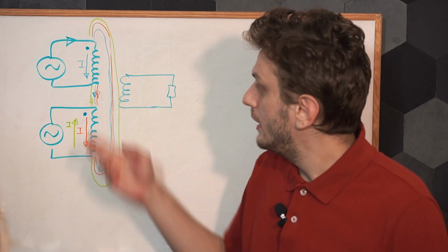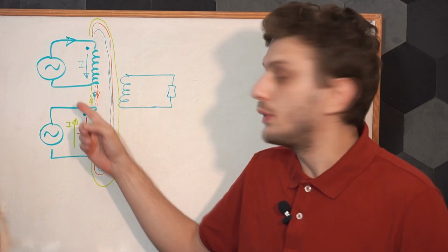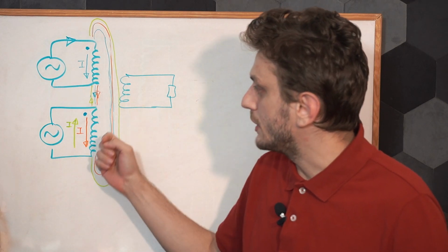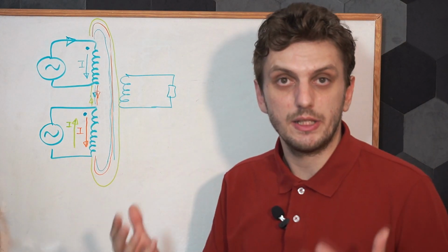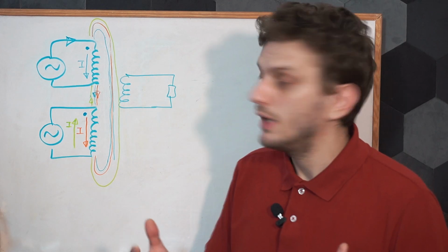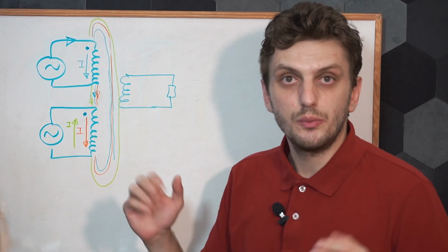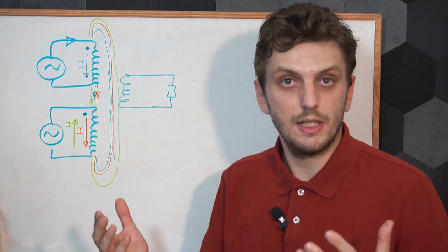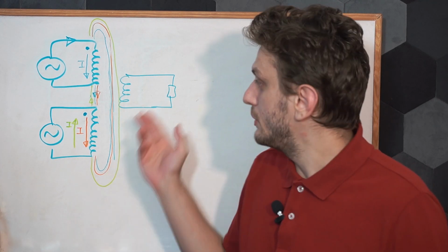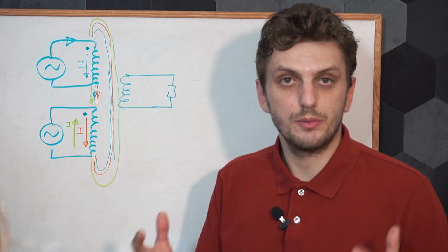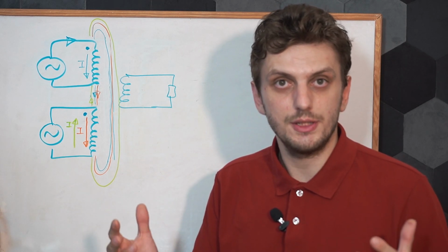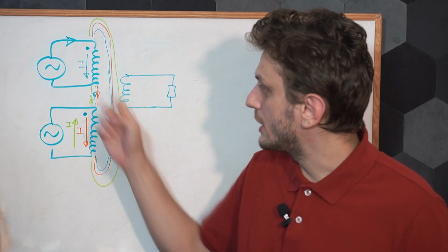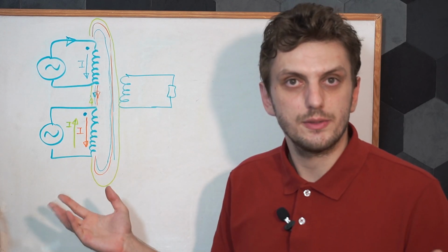On the other hand, if one coil has current going one way and the other coil has current going the other way, so two opposing magnetic fields are generated, then the secondary coil will see the sum of the two fields, which are opposing, so they will cancel out. Therefore, the secondary will see nothing. So we can perform the same addition and subtraction operations by using a single transformer with 3 coils.